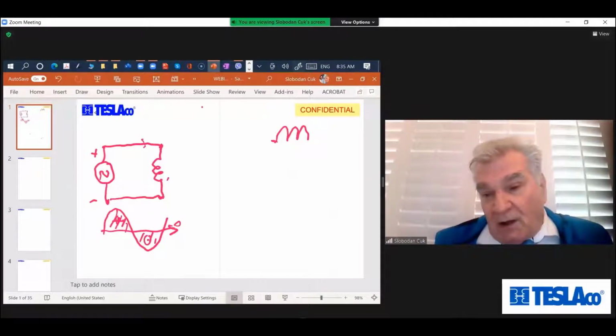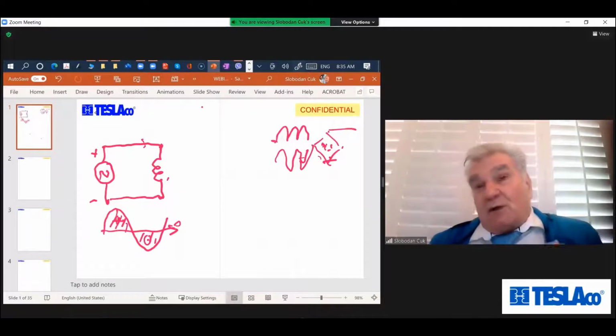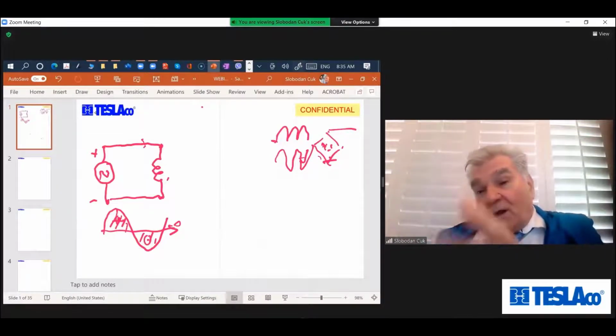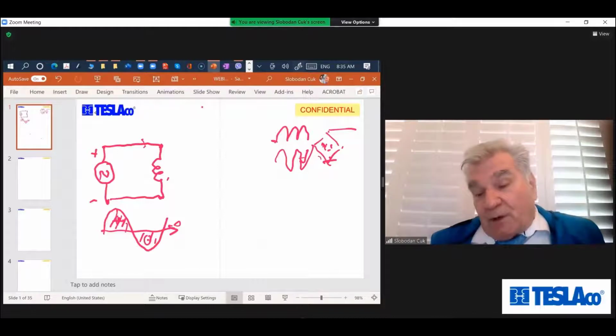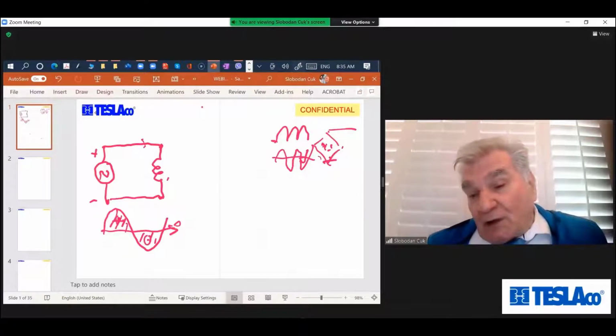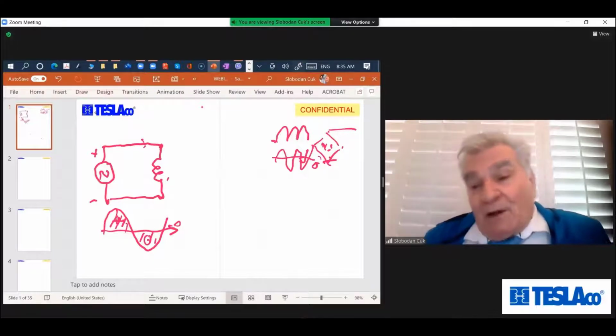Then we used the so-called active bridge to unfold it into the positive and negative parts. The active bridge runs at 60 hertz, so you use high frequency to generate the modulation, and then an unfolding stage with four active switches. But you have to make sure that there is no DC average.